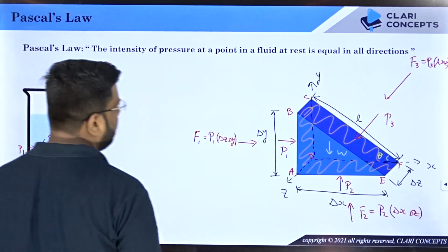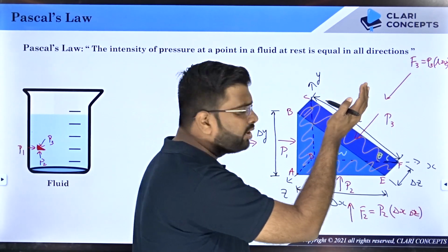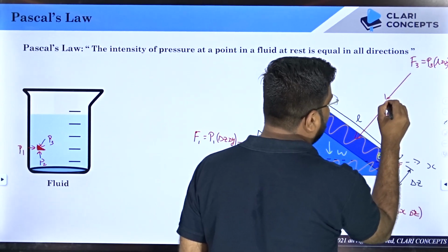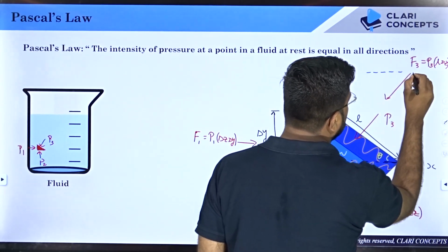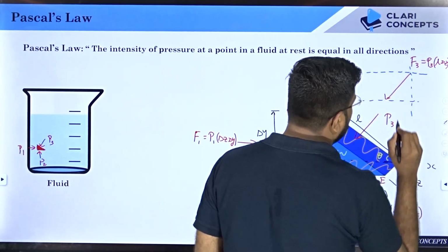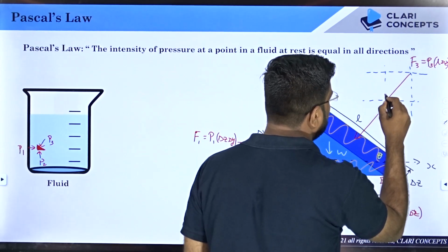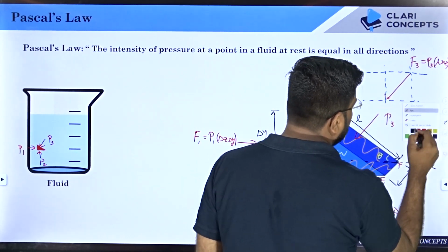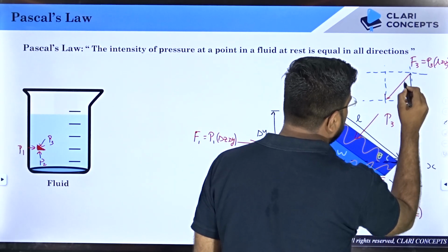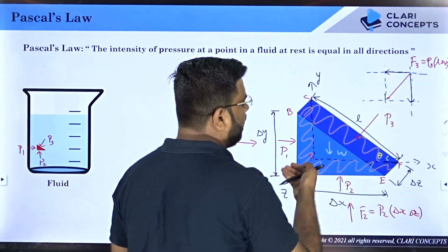Let me show it to you. Whenever you want to resolve this vector into 2 mutually perpendicular directions x and y, I will draw lines from the tail point and the head point of the vector parallel to x and y. Now you can easily see that one component of the vector will be from the tail to this point, and one component will be this. This component is along y, this component is parallel to the x-axis.